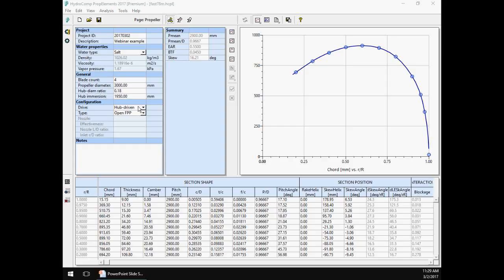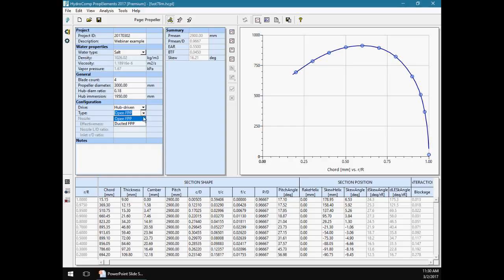And it has characteristics about the configuration, the kind of propeller that we want to model. This is going to be an open propeller, but we can also do a variety of ducted propeller options, including 19A, 37 nozzle, 2 popular ones. The 33 and 34 are decelerating nozzles. We can even put this into a circular tunnel, such as a bow thruster, or we can look at a representation of a high efficiency nozzle. And we'll talk about these other details a little later.